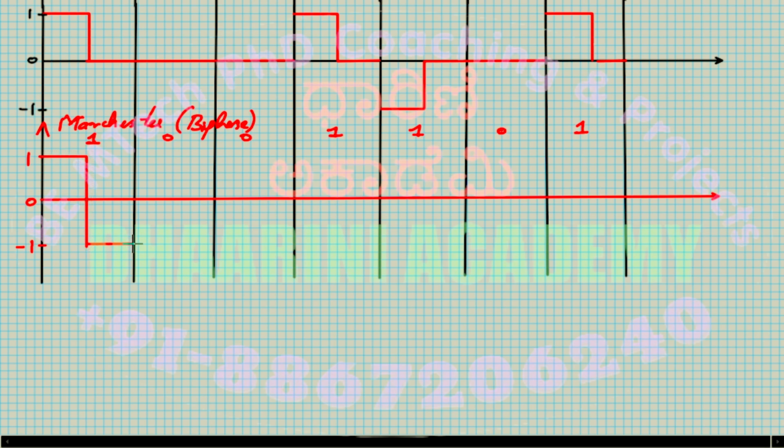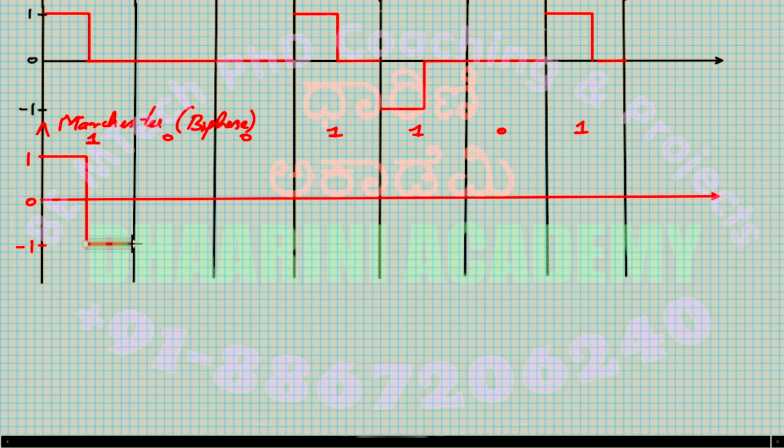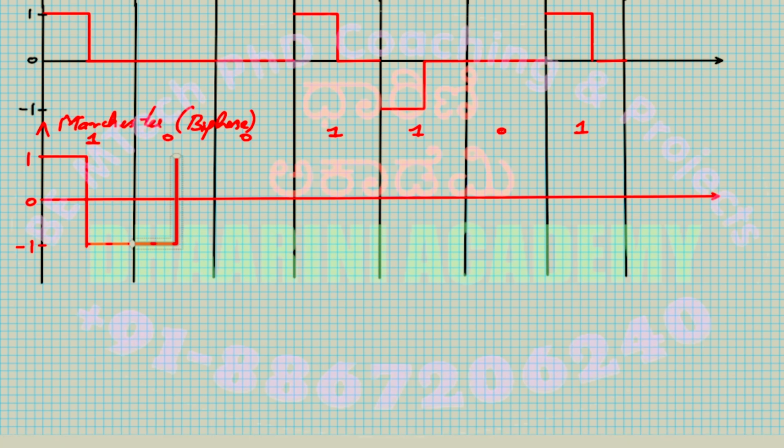This is the waveform. Now the biphase says that whenever 0 comes, you do the reverse. In the sense, first half you send -1, then remaining half you send the +1. Are you okay? Half of the waveform send -1, remaining half send +1. This is repeated throughout. That's all. I just have to remember this logic.